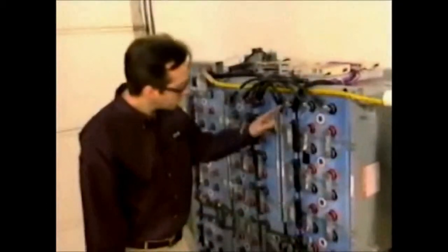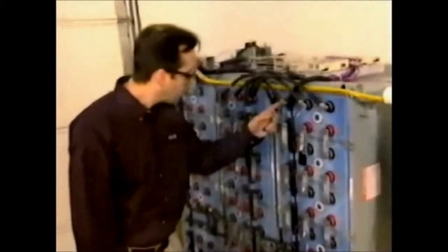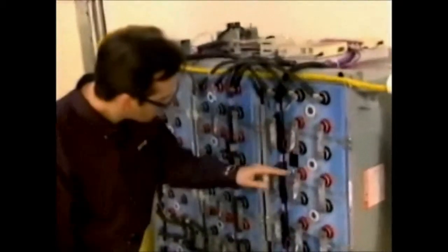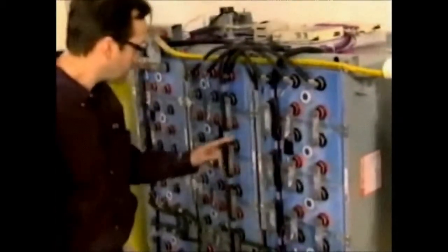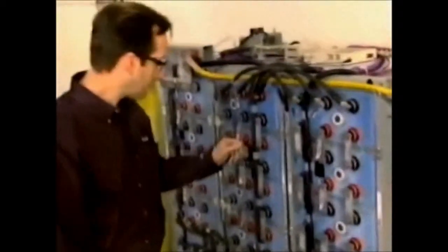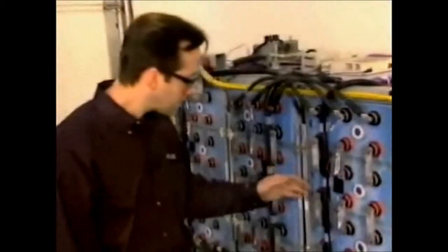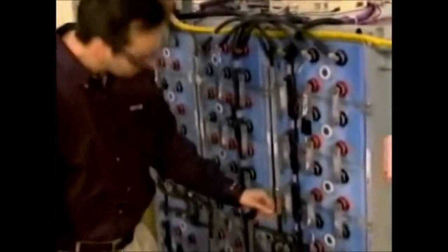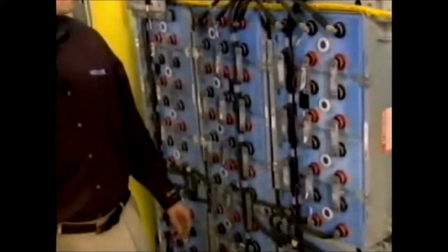We begin with a visual inspection. Look for evidence of battery problems, like post-seal leaks, positive plate growth, fractures or ruptures around the post areas, and cracked or bulging cases. Also smell for hydrogen leakage, a rotten egg smell. All of these are indications of serious battery problems, and while you're at it, make sure the hardware is torqued properly.